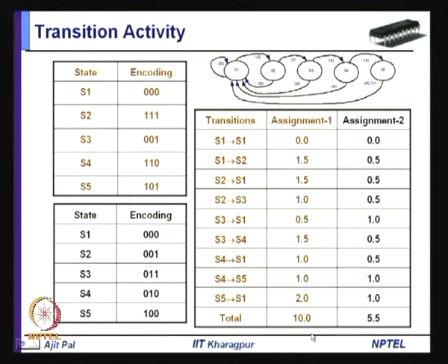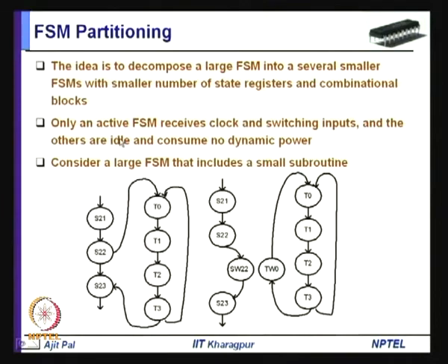So, we have discussed the state assignment. Now, we shall come to another important concept, that is FSM partitioning. Again, this was introduced by Benini and his colleagues. So, here the idea is to decompose a large FSM into several smaller finite state machines with a smaller number of state registers and combinational blocks. And only an active FSM receives clock and switching inputs, and the others are idle and consume no dynamic power.